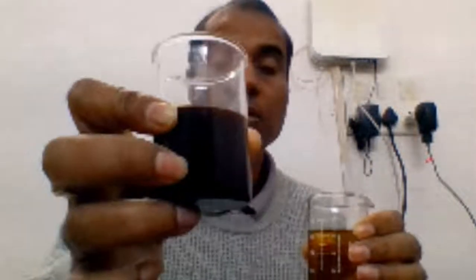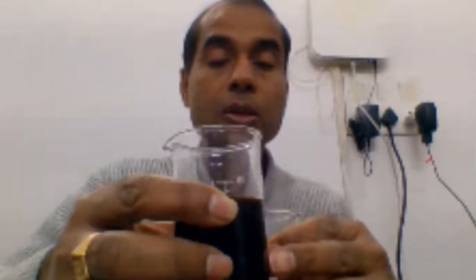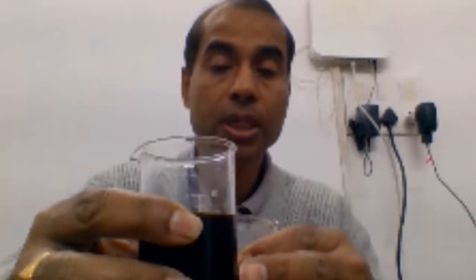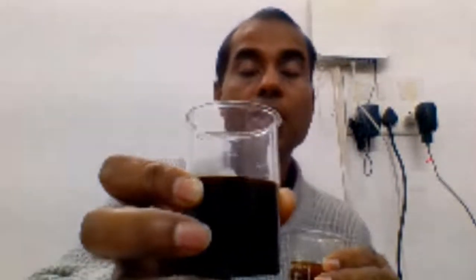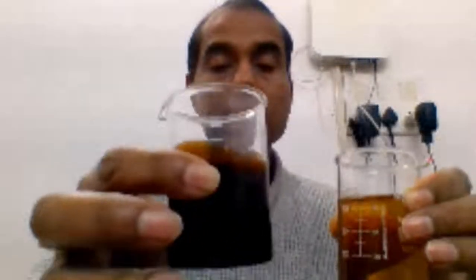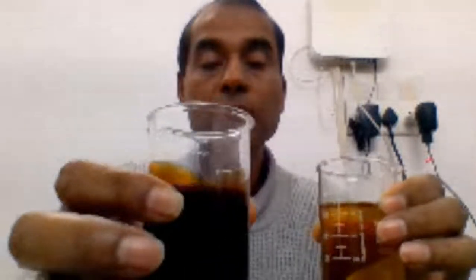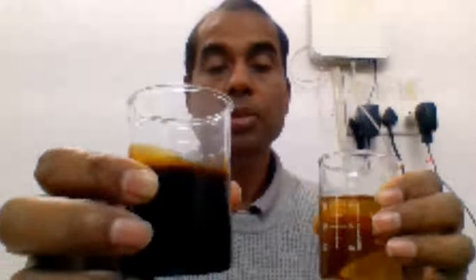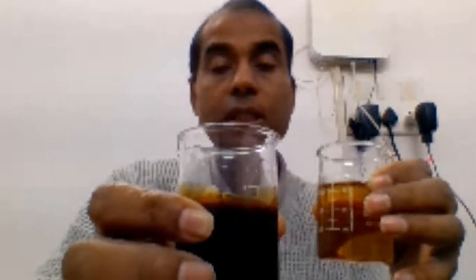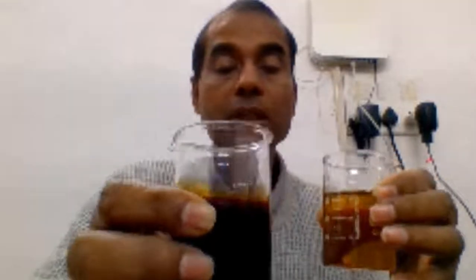Another thing you will notice is that this degraded oil doesn't settle down. I was talking about detergent and dispersant. Because of the detergent and dispersant, this oil is always in this form, no matter how long I keep it, in stable form. In terms of viscosity, it has almost similar viscosity. You see, I'm trying to shake. In fact, this has higher viscosity. This degraded oil has higher viscosity, which is good for lubrication. But still, we need to change it because it doesn't have those additives that this oil has. So viscosity doesn't go down, but its quality is not good.